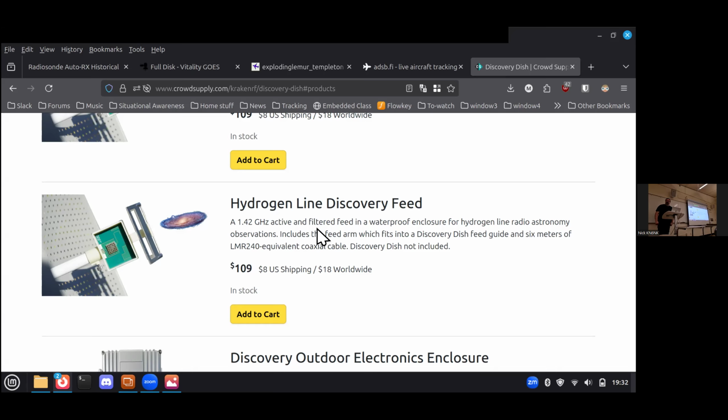Let's say you were to do multi-purpose receive, a bunch of SDRs connected to a single antenna. What would you say would be the best sort of wideband all-rounder antenna? A discone. The one that I have covers like 100 meg to 1.2 gig, and you can get larger ones that cover like 25 megahertz to 1.8 or 2.4 or something.